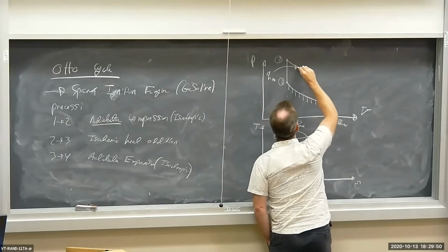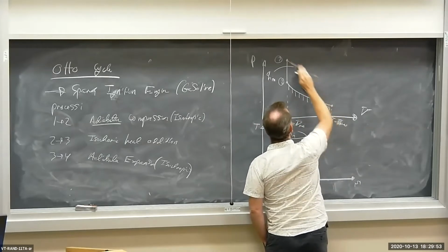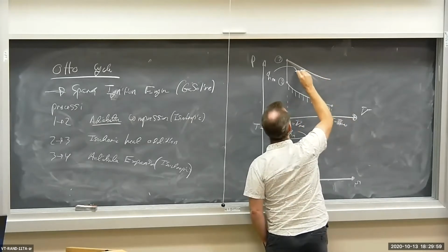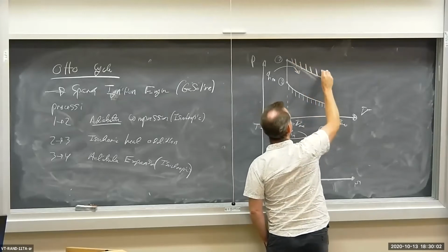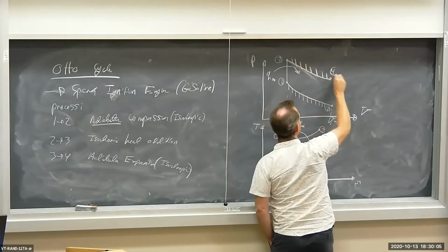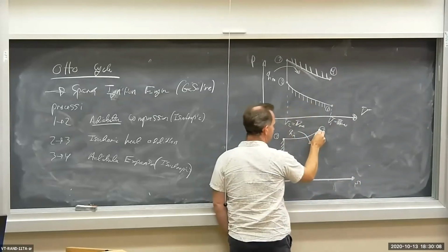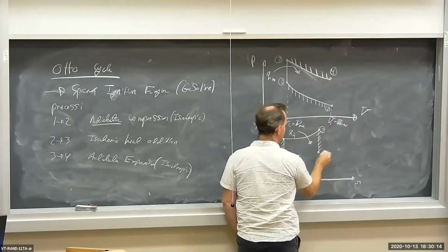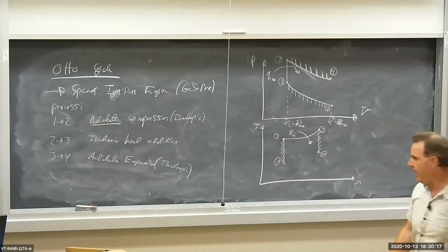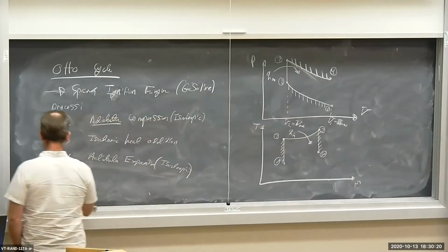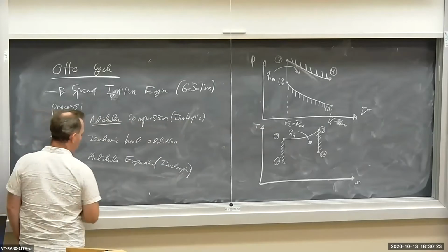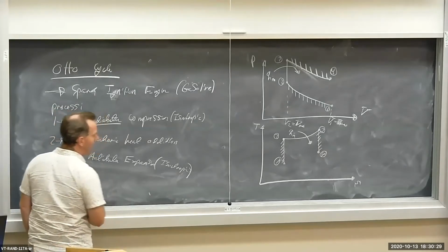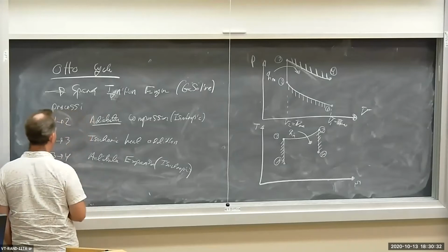So we have falling pressure, increasing volume, adiabatic, therefore isentropic to state 4. Isentropic expansion, temperature falls, no change in entropy because we have no heat transfer down to state 4, okay? Then to get back to state 1 to complete the cycle, 4 to 1, we have constant volume or isochoric heat rejection.